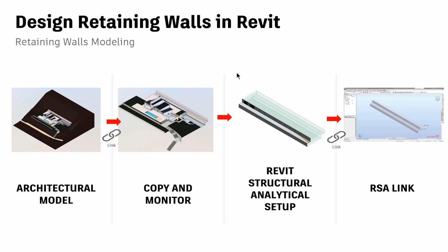How to design a retaining wall in Revit, where I will take the Revit architectural model from Lina. I will then link it to a brand new structure Revit file, and I will copy and monitor the wall that she established in the back of the building. I will show you in the demo. And I will take the wall and set up a Revit structural analytical file with load and some support and so on. And from that, I will link the Revit model into SA to do the analysis.